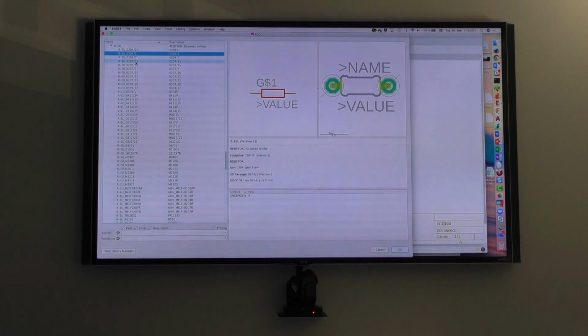The body of the resistor has a diameter of about 2 millimeters and a length of about 4 millimeters. And the grid is about 5 millimeters. To be honest, it's not 5 millimeters, in inches it's 5.08 millimeters. So that's an approach to describe what this should be. And there's nothing written like a quarter of a watt or whatever.